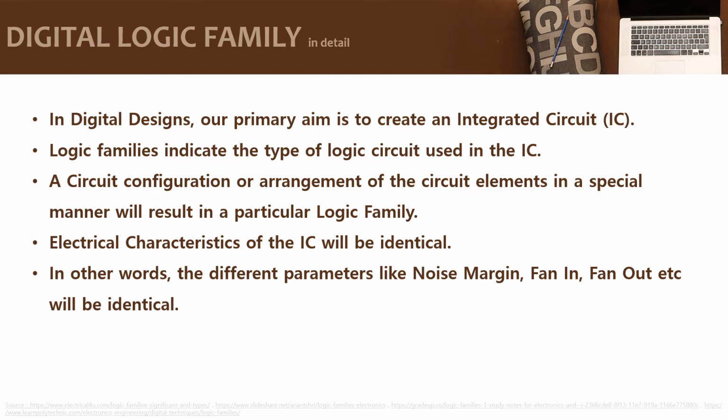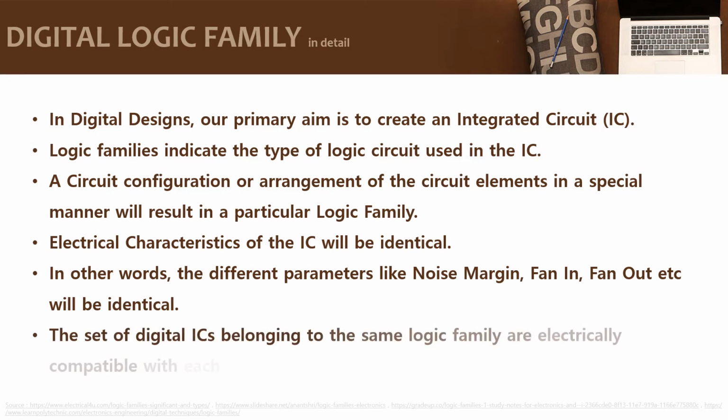Also input output logic levels, current sinking capability, current sourcing capability, noise margin, fan in, fan out can be taken into consideration. Many different parameters are there. And so the set of digital ICs belonging to the same logic family are electrically compatible with each other.